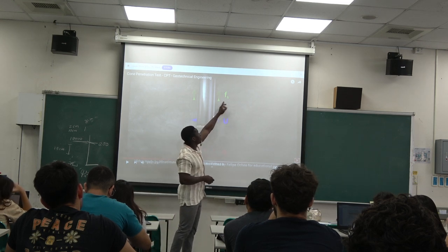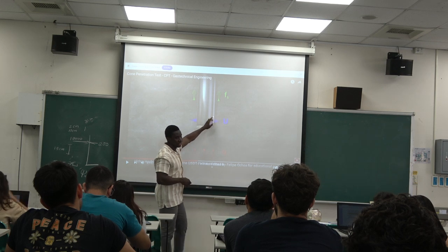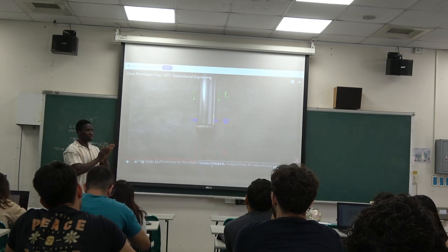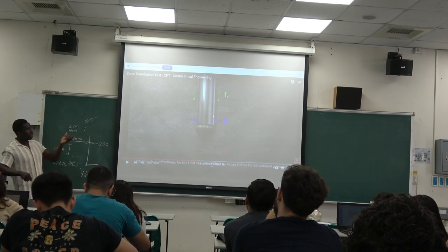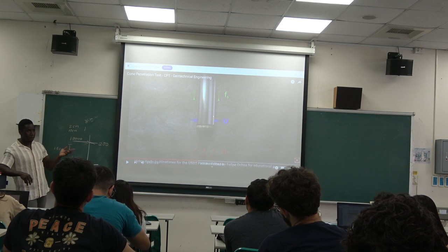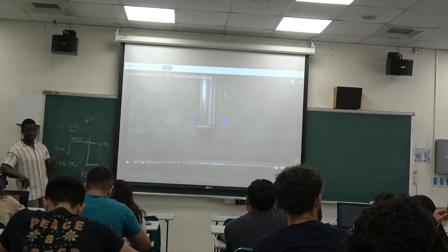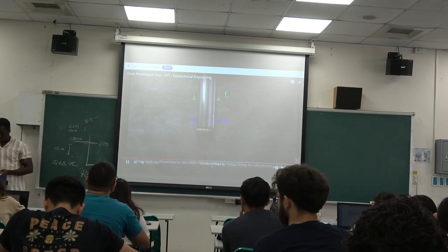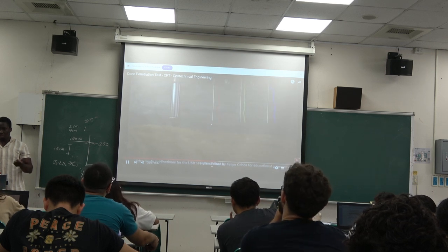And another parameter that you can calculate from the CPT is the Fs. That is the friction between the sleeve and the soil. Okay, so you can see that from the CPT you can actually get more parameters. You can even get the pore water pressure, unlike the SPT. So the concept for the CPT is also similar.